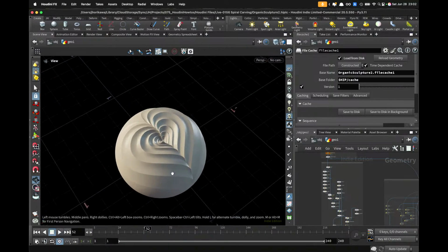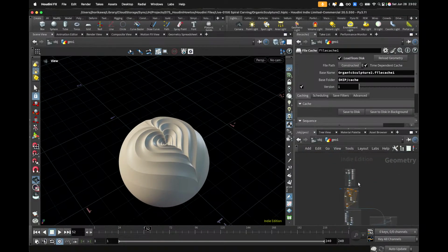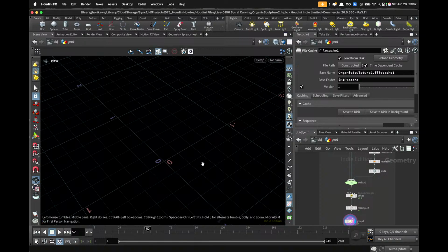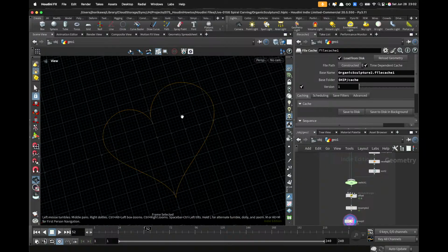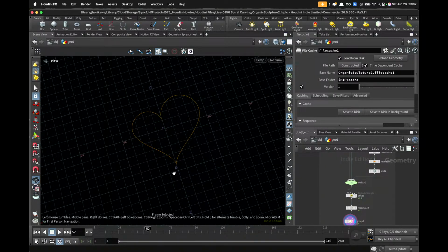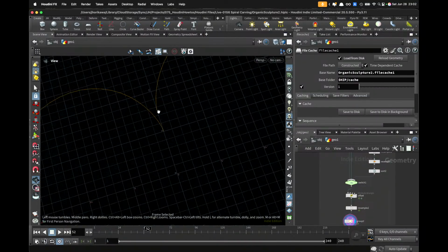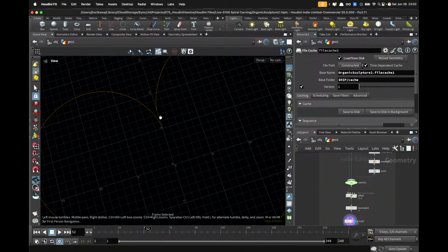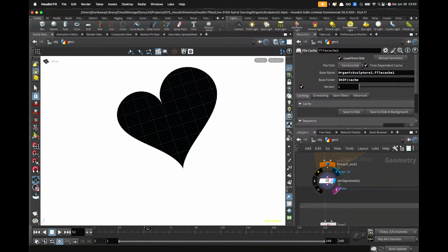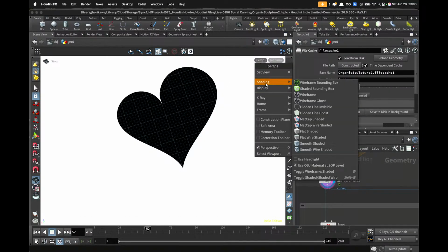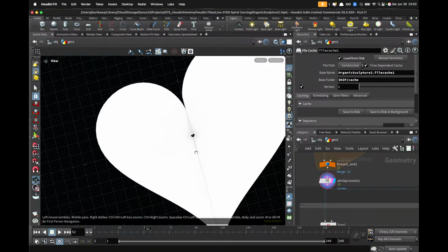So basically what I'm going to do is to prepare a 2D curve which looks like just a simple pattern like these, and continuously create a connection between these closed curves by first of all trying to open it with some gaps, and recursively continue connecting it as a spiral curve, which in the end looks like these in a mesh.